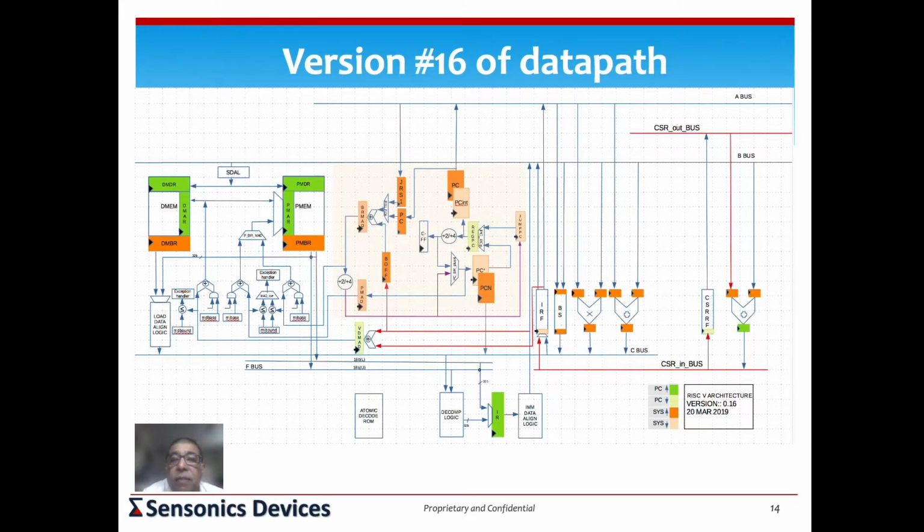And you can see on the extreme right, there is one piece which has a plus written inside. That's the ALU, arithmetic logic unit. There are two pieces which have the plus written on them. Look at the one which hits the C bus. That's the one I'm talking about. That's the ALU. Next to that is a cross. That's the multiplier. Then there is another piece of logic called the barrel shifter. And then there is the integer register file, which is the IRF.